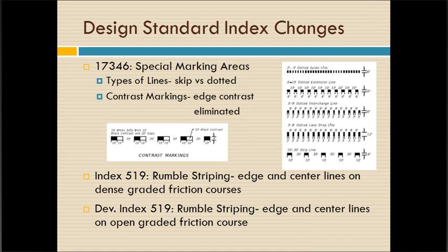We started off with setting the stop at the same spot that we use for dense graded for open graded. And that depth is approximately a 1/2 inch deep. Now, if you're not familiar with open graded friction course, it's a very open mix with rock up to a 1/2 inch, and the open graded friction course is 3/4 of an inch in depth.